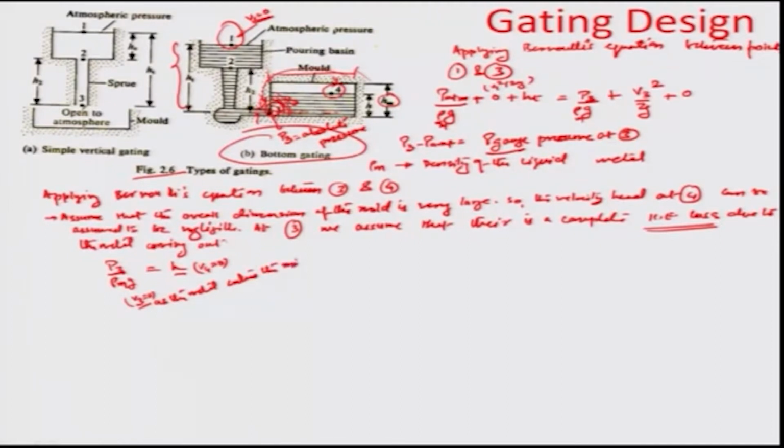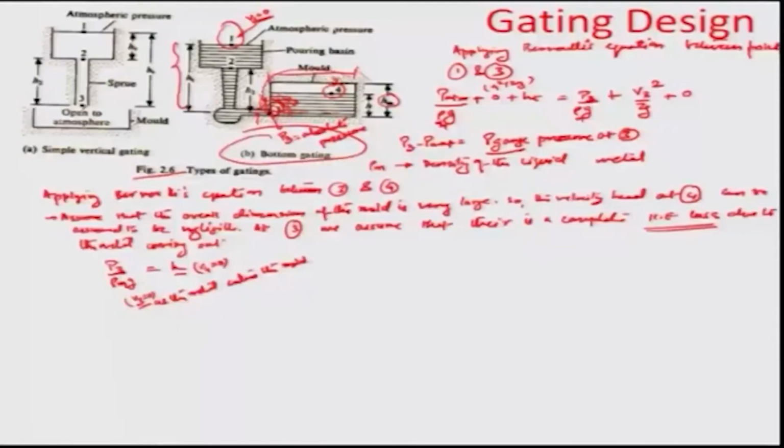So, this is just about the same instance of time, the only thing is it has just entered the mold from the cross sectional area, and we are assuming that the amount of kinetic energy delivery to the mold is negligible in comparison to the overall mold sizes, etc. So, sorry, the kinetic energy is negligible because of the overall largeness of the mold size, etc., and it is as if a few droplets are emanating from that small gate region into a bigger mass of fluid. Okay. So, the kinetic energy addition is very, very low, and so we are assuming this V 3 beyond the gate region to be equal to 0 for that case.